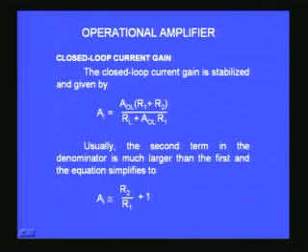And if you look at the closed loop gain, the closed loop gain will have to be AOL multiplied by R1 plus R2 divided by RL plus AOL into R1. But in this you would find the AOL R1, AOL which is a large number multiplied by R1, will be a very large number compared to RL, and therefore I can neglect the effect of RL, and then the AOL will cancel, and what I get will be R2 divided by R1 plus 1. So that is R1 plus R2 by R1, which I rewrite like this, R2 by R1 plus 1. So the gain of the amplifier, in this case the current amplifier, is 1 plus R2 by R1.